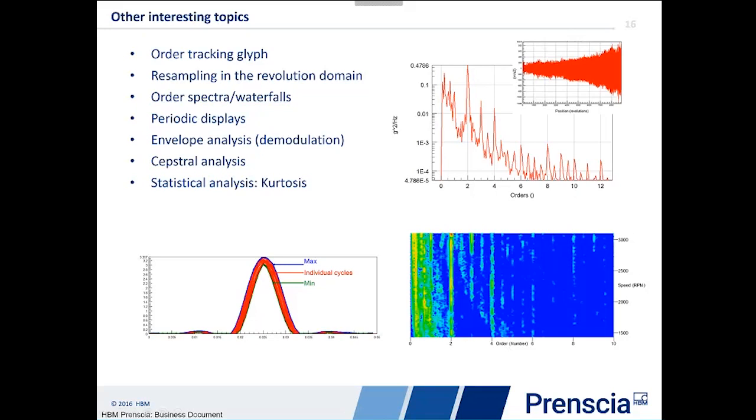So you may find a plot like this one where all the curves overlay nicely, you see, and we've got running statistics that can extract the maximum envelope, the minimum envelope, the mean value, on a cycle-by-cycle basis. That can be very interesting for pressure fluctuation inside of a cylinder or things like that. Every phenomenon that occurs at every revolution, and that's meant to be periodic.